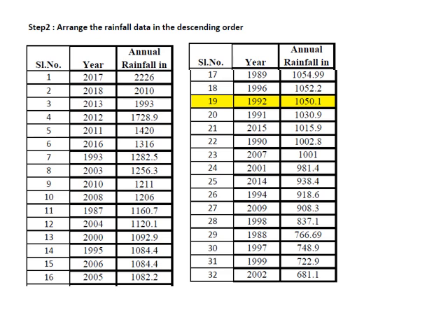That's the reason why we go for what is known as the dependable rainfall, and then decide the storage volume. For that storage volume, we go for the design of the bund after fixing the normal reservoir level as well as the maximum water level.